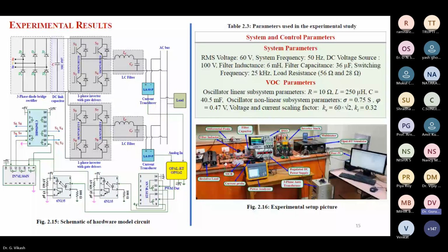And if you have a Semikron inverter stack, there is no need to design any gate drivers. By default, gate drivers are there for all these 8 switches. Okay, 4 gate drivers are there. Each gate driver will generate 2 signals. Two switches make one leg, and for each leg, one gate driver is there in the Semikron inverter stack.